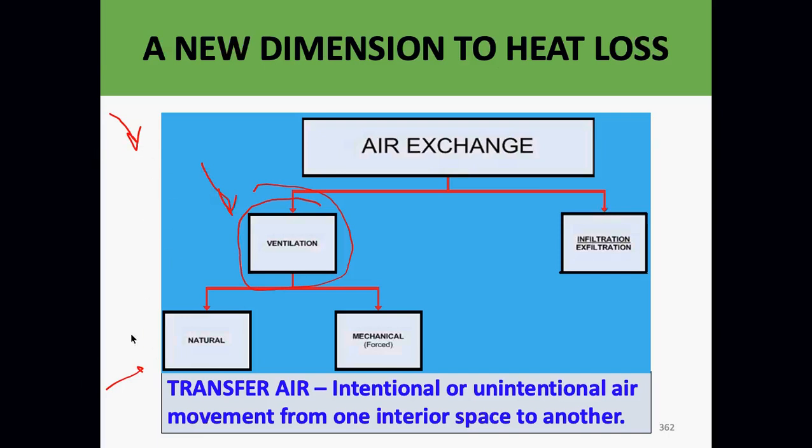Again, in both times of year, I can cause air patterns in a house if I do this properly. Natural ventilation is used very heavily in European countries. They know how to do it. Here, our contractors much prefer mechanical ventilation. It's easier, you don't have to size it as well, and you don't have to understand buildings. They stick in a ventilator fan.